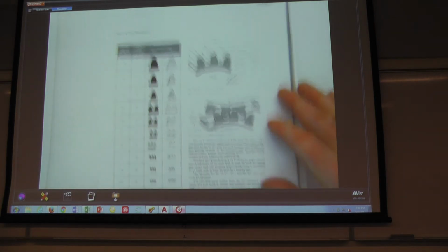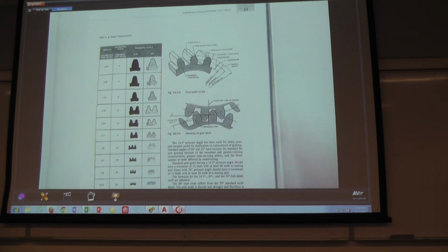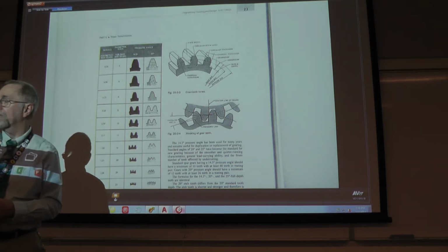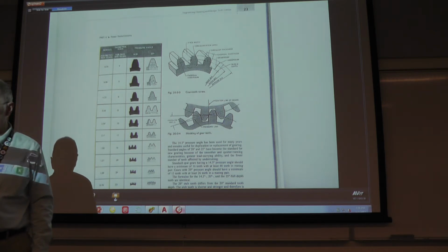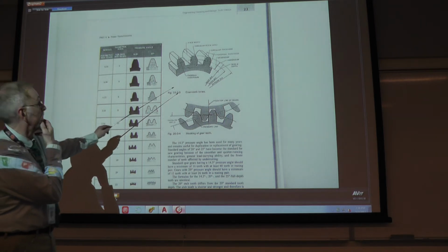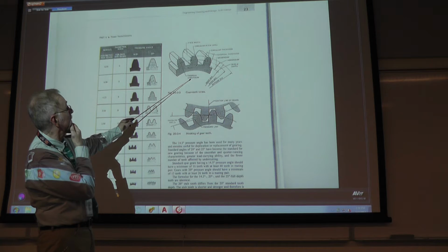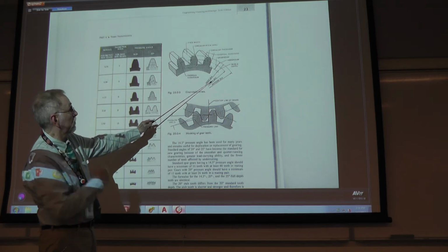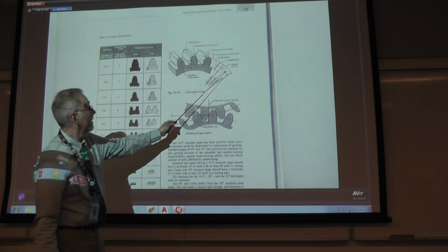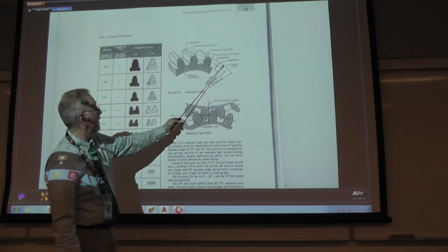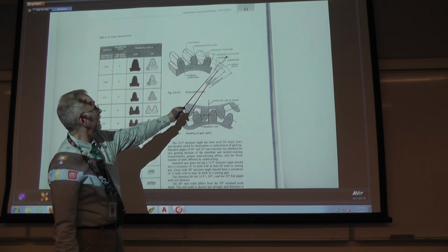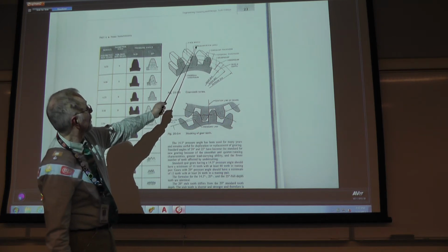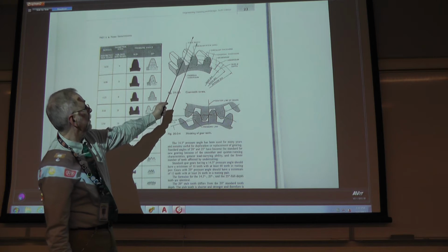And then there's some gear terminology in here that you will be using when you get to the formula. Of course, there has to be a little math involved in here. The formula and how to calculate some of the sizes that you would specify for a particular gear. There's something called a chordal addendum. There's a root diameter, there's a pitch diameter, there's an outside diameter. There is a hole depth, which is basically the height of the tooth itself. There's an addendum, a dedendum, a chordal thickness, a circular thickness, circular pitch, and face width.